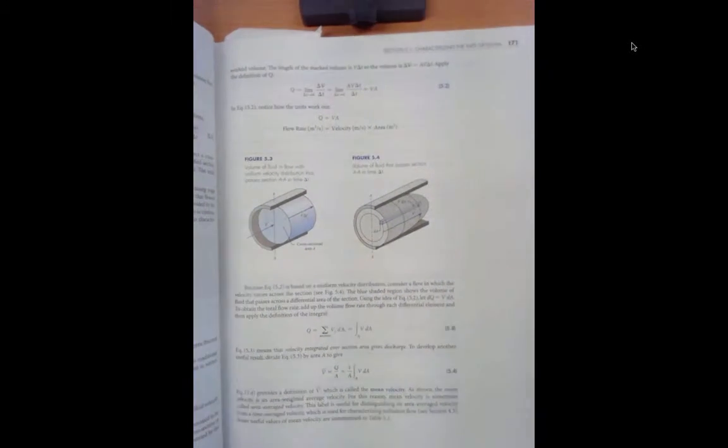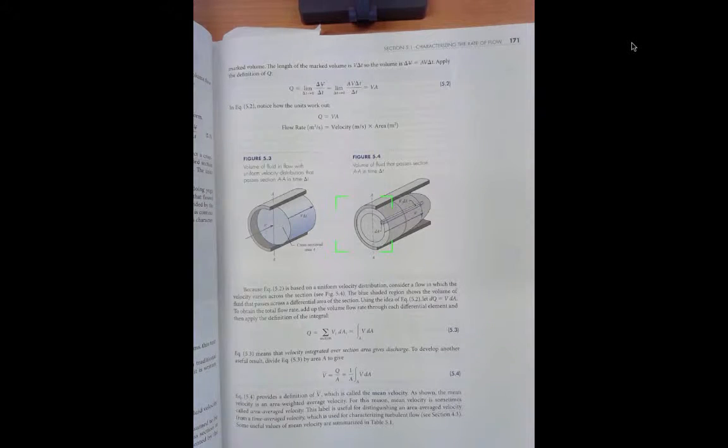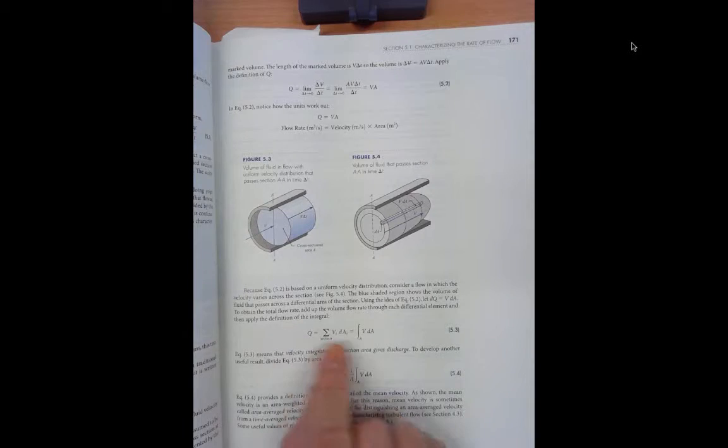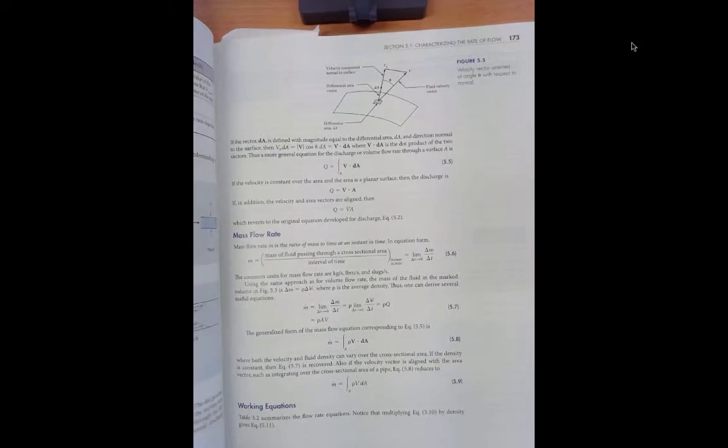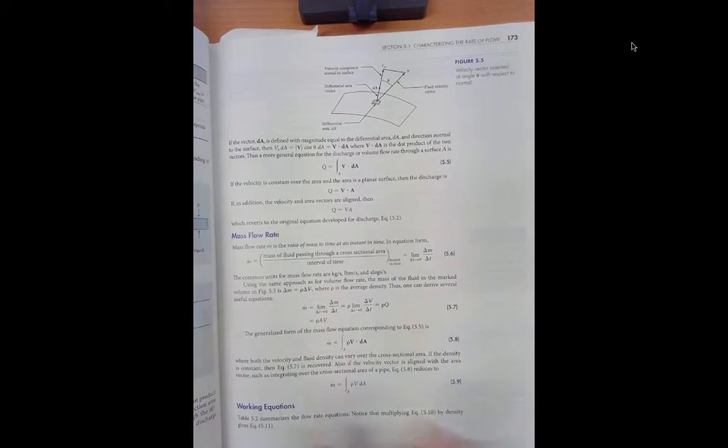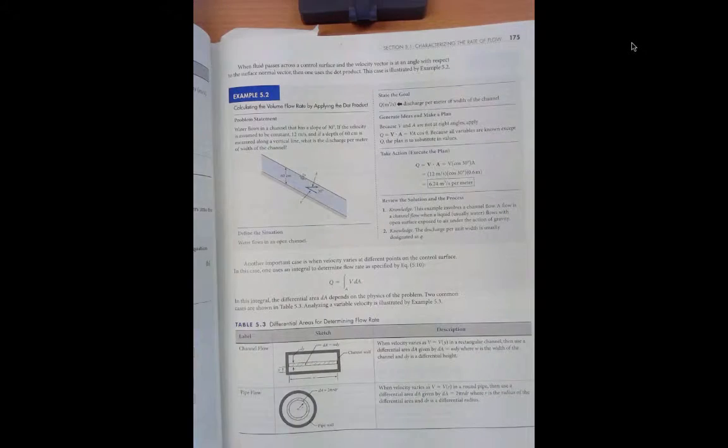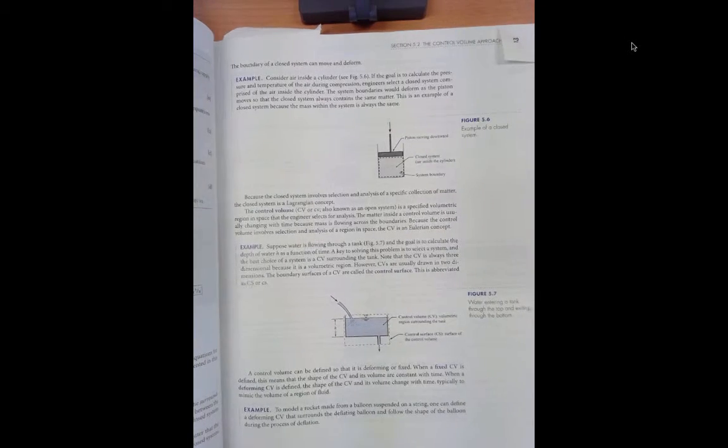There we go. Let's get some focusing going on here. Well, you can actually see that now. And as we just did, Q is equal to the integral over the area of the velocity inner product with the area vector, and alternatively, the definition of average or mean section velocity V bar is Q over A. We did the same for mass flow rate already,